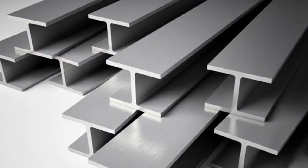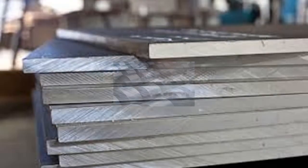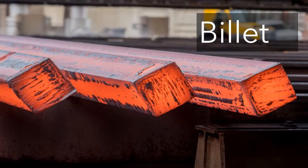Some of the rolled products made of steel: products such as structural shapes and rails are rolled from blooms. Plates and coils are rolled from slabs. The bars, rods, and related geometries are rolled from billets.